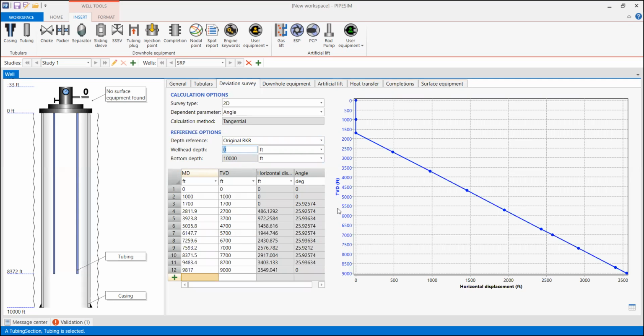Okay. Also, you need to know that a sucker rod pump will perform best actually in a vertical well. If you have a deviated well, there will be maybe a problem. Maybe there will be friction between the tubing and your rods, right? Where the rod is going upward and downward, there will be friction. But right now it's okay. We will still try to construct a deviated well because in general, actually, we still have a lot of deviated wells equipped with sucker rod pump.